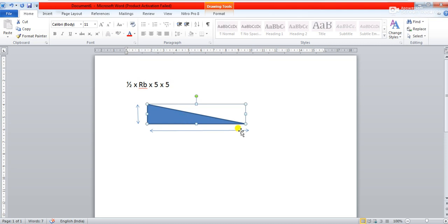Now where you will have to find out the displacement? You will have to find out the displacement at this point, right? This is actually your point B. So if you want to find out displacement at this point B, then from moment area theorem, what will be there? So basically you will have to divide it by 1 EI, because moment area theorem always you will have to apply on the M by EI diagram, not on M diagram.